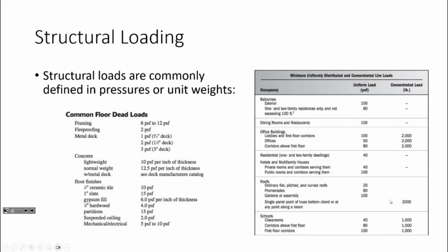What about live loads? Okay, so when we were doing influence lines, I gave you a definition about dead versus live that was analytical. And so what I meant was dead loads are permanent and live loads are transient. Live loads have the potential to move, right? And that's still true, okay? But we're starting to dip our toes with this lecture a little bit into structural design, like what you would talk about in steel design or what you would talk about in concrete design. And live loads, from that perspective, the word I like to use is occupancy. A live load is prescribed based on what the structure is being used for.